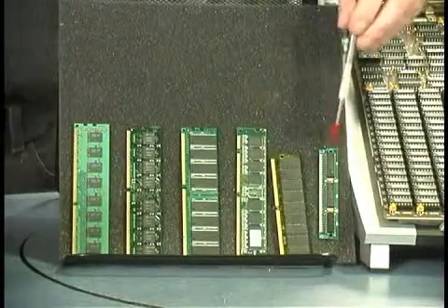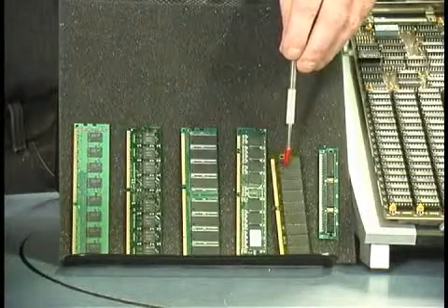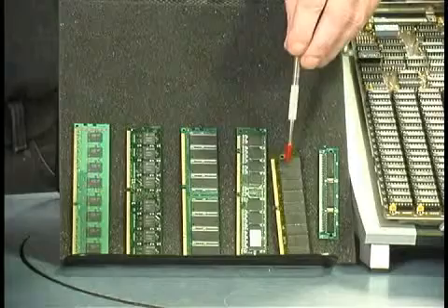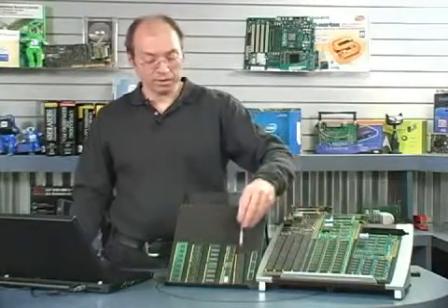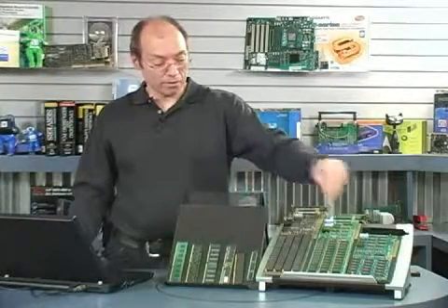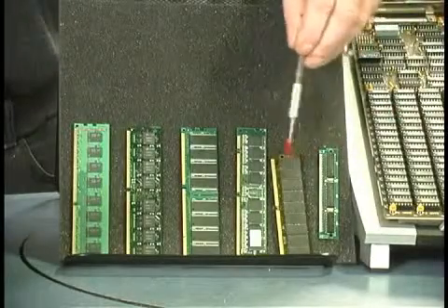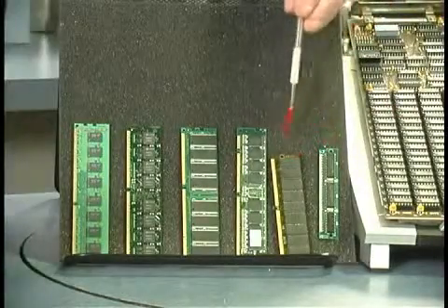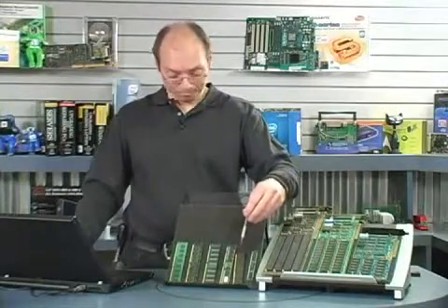Well, from the 30-pin SIMs, we went to the 72-pin SIMs. This is an example of a 72-pin SIM. This one happens to hold 8 megabytes. That's 4 times more than this entire card in just this little memory module. Now, back then, these modules ran at 5 megahertz. The board ran at 10, and these modules ran up to 16 megahertz. That was the top speed available for memory at the time.